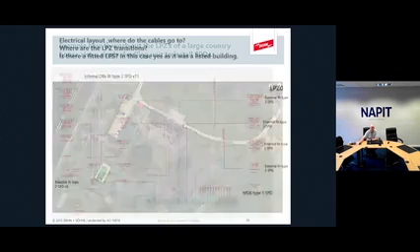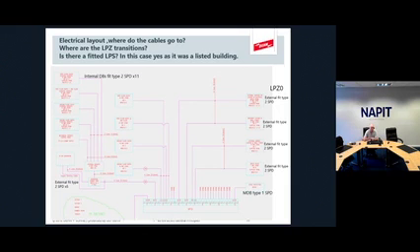is the electrical schematic. So in this installation, because it has lightning protection, I need a type 1 at the origin, where my main distribution board is down the bottom there. Then on the right hand side, I've got some cables going off to external locations. So they at the far end will have type 2 SPDs because they've left the internal zone, which is protected. Then on the right hand side, we've got some internal consumer units, distribution boards. So they all have type 2s within them as well. And then down the bottom, we've got 5 other SPDs going off to the cottages, stable lot, garage, that sort of thing. And at those far ends, they're going to have type 2s as well.